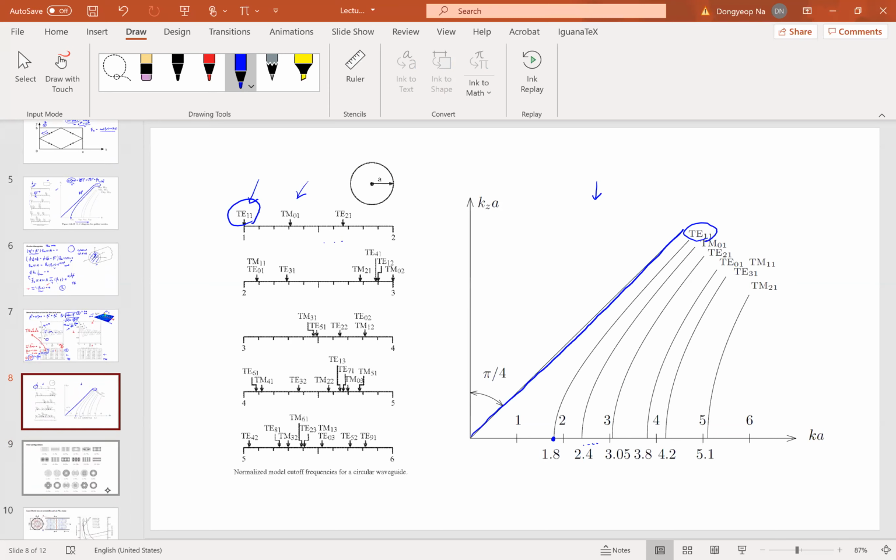By the way, we were focusing on this scalar field, right? Transverse plane. We studied how to find the closed form of this solution for rectangular waveguide and the circular waveguide by solving the transverse Helmholtz wave equation. Then we can construct the whole solution by using this equation.